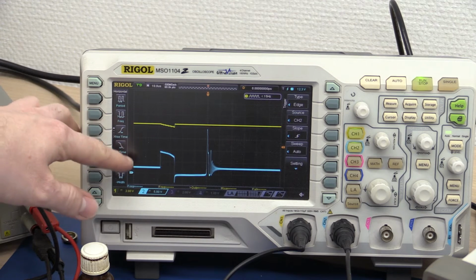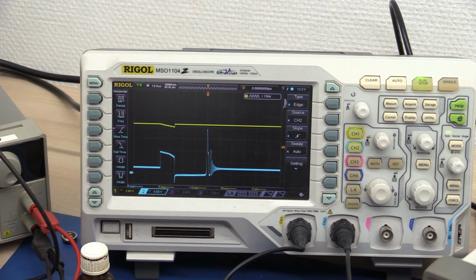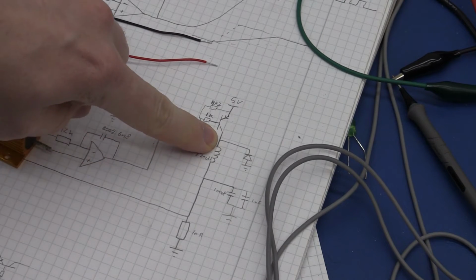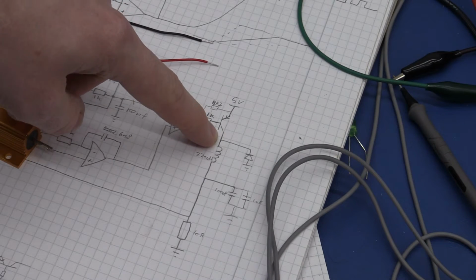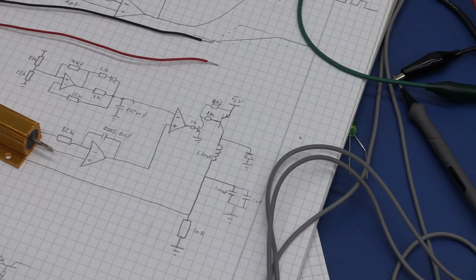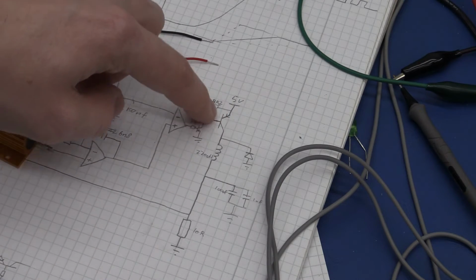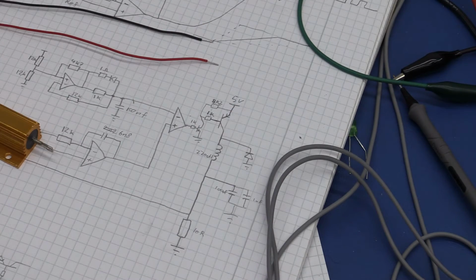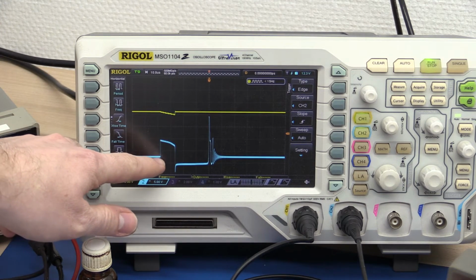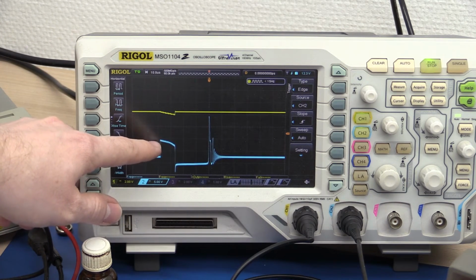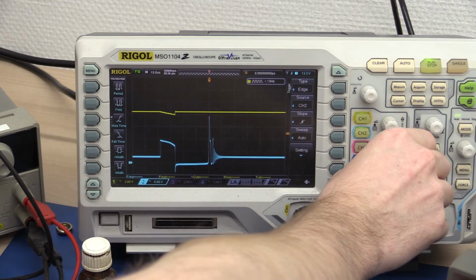If we see the scope here, the yellow line is VCC and the blue line is on the collector side of the pass transistor. So that would be right here. When the transistor is on, we expect this voltage to be approximately the same as VCC. It has a little bit of saturation voltage, it should have that, but in a good circuit we would have as little as possible. But you can see in this case here, when the transistor switch is on, it goes to VCC. I can scale it up.